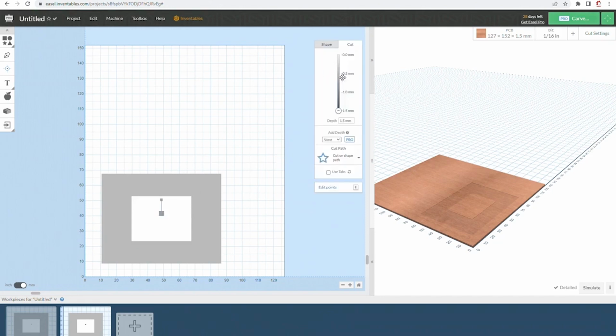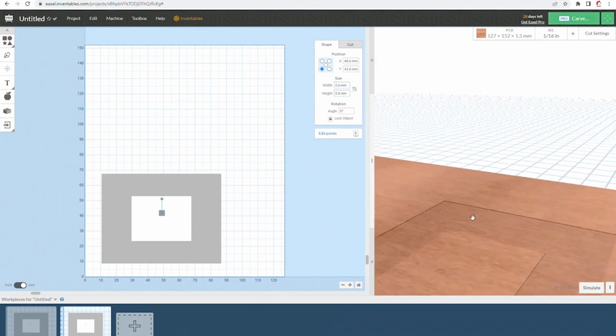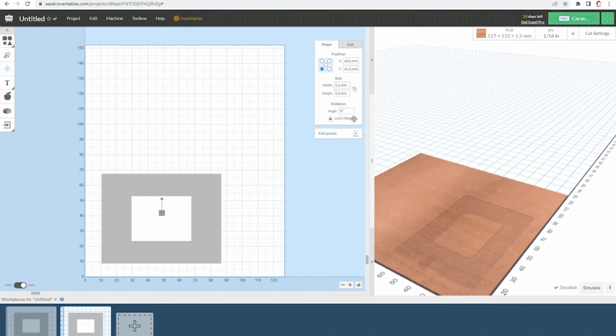Last part is the probe feed. It currently does not show up, so it needs to be adjusted to 0.6 by 0.6mm so we can see it. But as our bit is a bit bigger than that hole, we'll remove it and drill it manually.